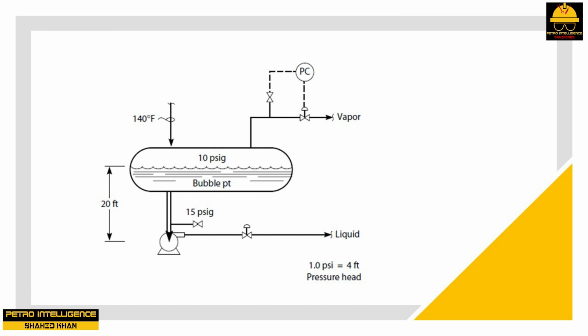You will see that the pump suction pressure will drop and then come partly back up. If the pump suction pressure were 15 psig to start with, it might drop to 12 psig and then come up to 14 psig. The permanent difference in the suction pressure between 15 and 14 psig is due to a 1 psi piping friction pressure loss.